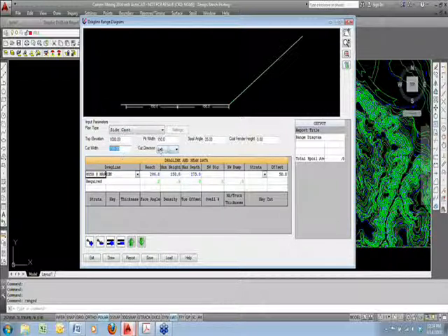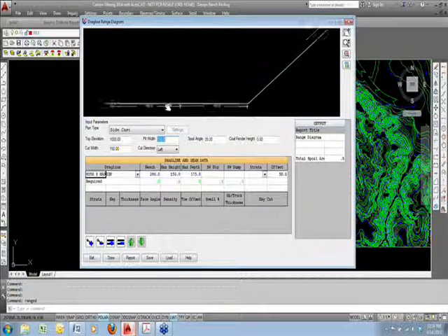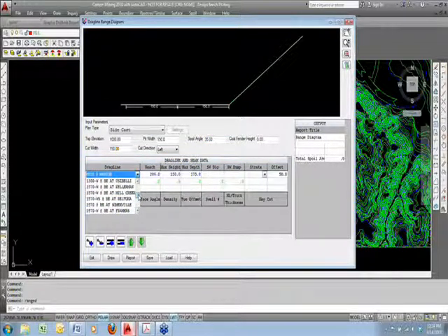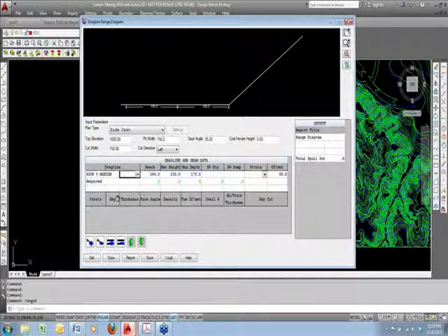You set up your initial cut and pit width. So that would be this is the open existing pit, and this is the future cut, 150. Everything's labeled up in the preview. You set up your initial spoil angle in degrees, and you choose your drag line down below. There's a list of about 40 drag lines included with the program. These are the same that are used with the cut in place, and you can also add your own to this list. And then you start by adding the different seams and drag lines down below.